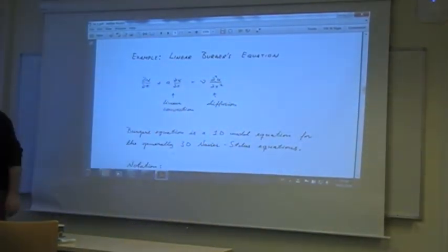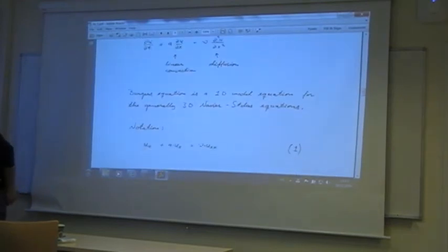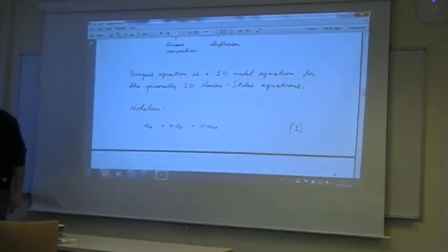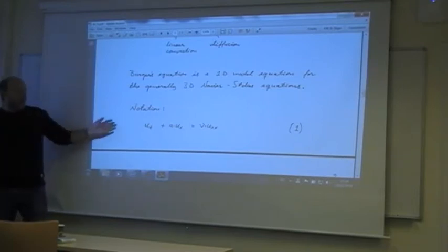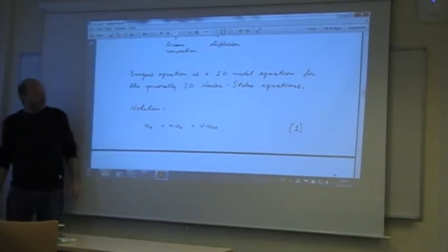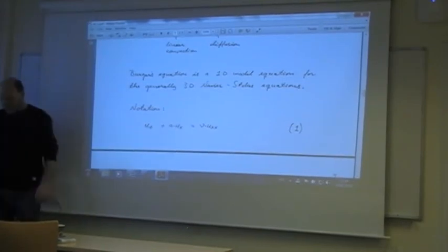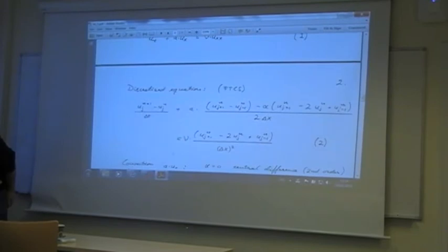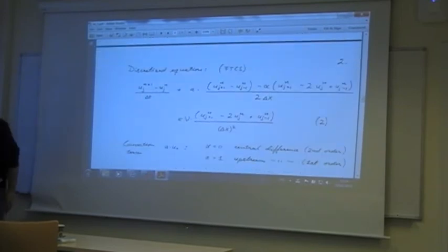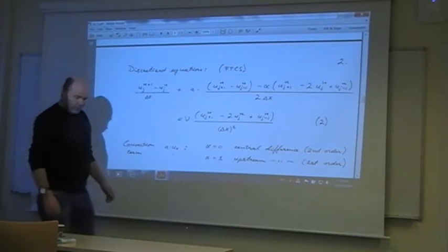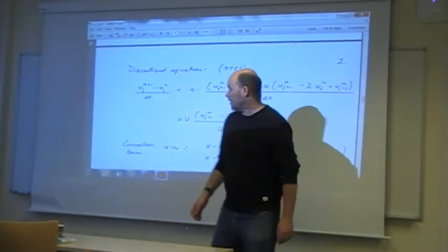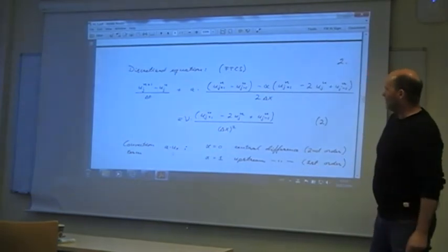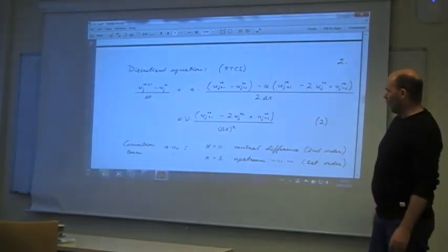So for this material here, you will see how you can achieve the modified equation after creating a numerical scheme of this Burgers equation. Here also I use the subscript for derivatives, and then we start out creating a forward time, but then here is a combination of central and first order upwind scheme.